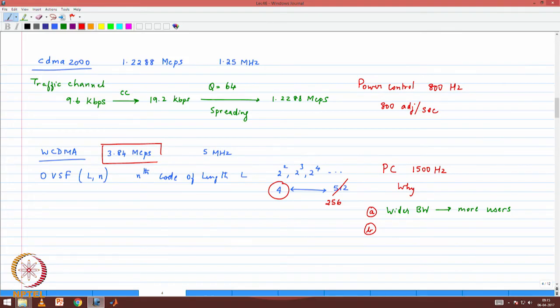So you want to control these users. Typically in a wideband CDMA system, somebody with spreading factor 4, because he does not have much processing gain, will be transmitting with higher power than the one who is using spreading factor 256. Does that make sense? Because he's got more data to send, you have to use more power to get your data across, right?